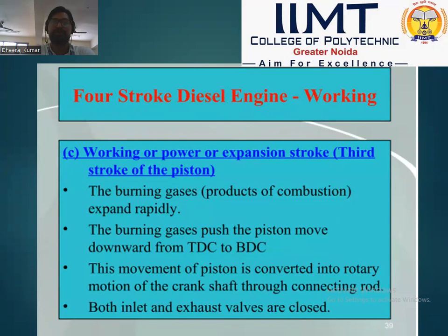Both inlet and exhaust valves are closed. The third stroke is called the expansion stroke. At the end of the compression stroke, fuel is injected and burned. The hot gases generated apply pressure force above the piston, and the piston moves rapidly from TDC to BDC. This stroke is called the expansion stroke or working stroke.